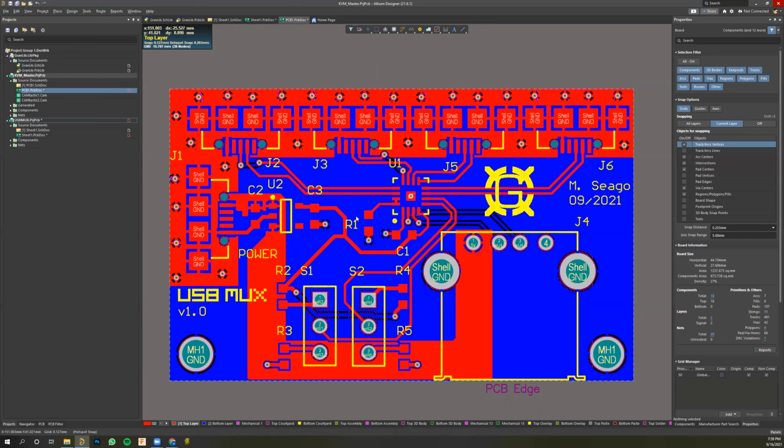Cool. So if we're good here, I don't know what else to say about this. We didn't design any of the footprints, we already did that. It's just a matter of placing them. When you're placing a capacitor, you want it to be close to the device it's associated with. Resistors aren't such a big deal as far as closeness.